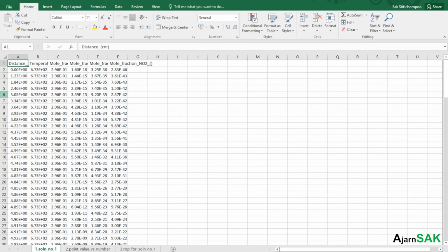For example, you said my reactor is this long, from 0 to 10 centimeters. And you give an initial estimation of how fine your grid should be. You say make it 1000 grid points in here. What I mean is here you will see all your solutions from 0 to 10, but not necessarily 1000 points. It resolves them based on its own solution method. This is just your initial estimation of how much you divide it. So the initial grid will be 1000,